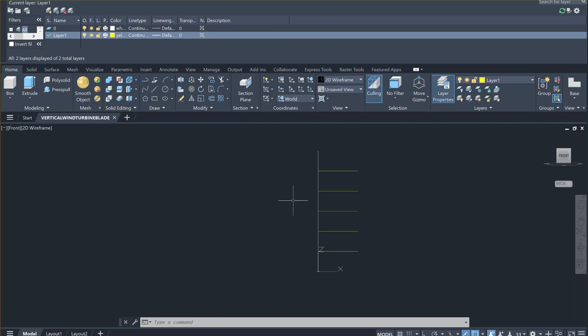Remember I said in the very beginning that you can create only the regular lines, ordinary lines, and circles and ellipses on XY plane. That's the rule in general. This is the way AutoCAD is created, so we cannot argue that rule. So we type UCS, enter, and then we type V for view, enter. So UCS corrected itself to the view so that I can see X and Y plane right in front of me. Now I can go with the ellipse command, select the center point and 2 radius ellipse option,